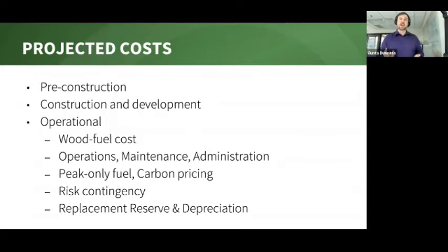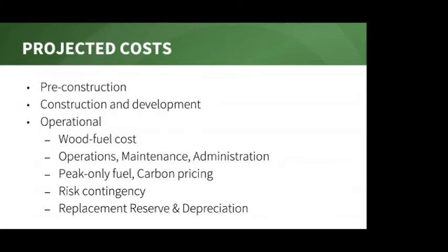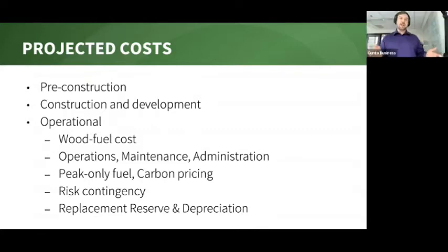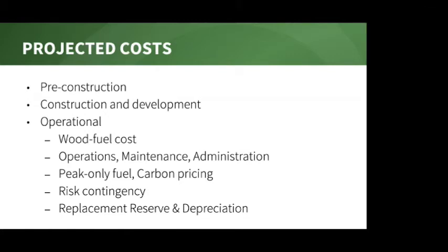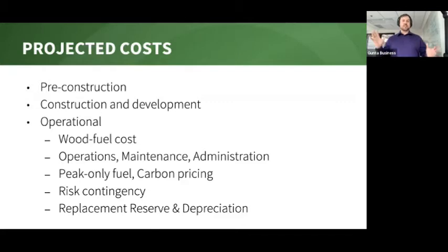We're recommending an array. So you can have 2, 4, 6 in an array. Let's say you have a general 400 kilowatt operating requirement. You could have that in 4 or 6 units, all at 100 kilowatts each. And they will basically computerized scale in and scale out, always each unit operating at near optimal efficiency. And so we're not getting the creosote buildup because we're not having to go to those extreme high heats. It's always optimized specific to that unit.